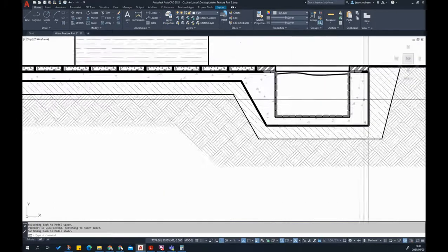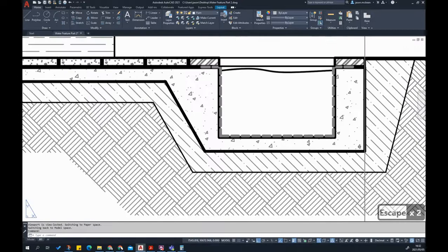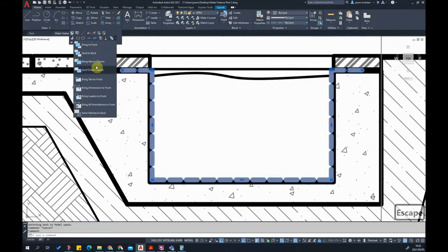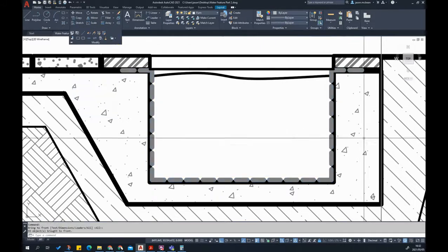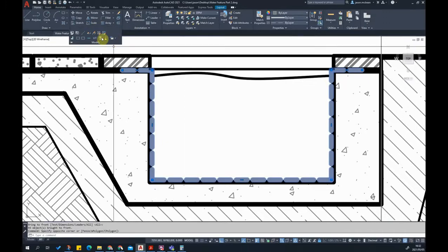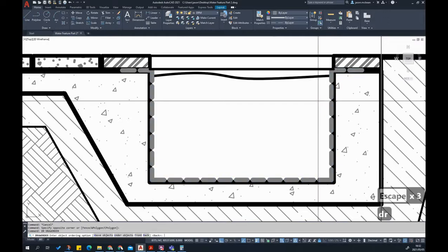Great. Here we can see our DPM layer, that layer in the background. Just remember, display order, draw order. If it looks funny like that, you can use your draw orders. So bring objects to front. You can change the draw orders of these objects. The shortcut key is you just select this object, draw order, and say F for front.